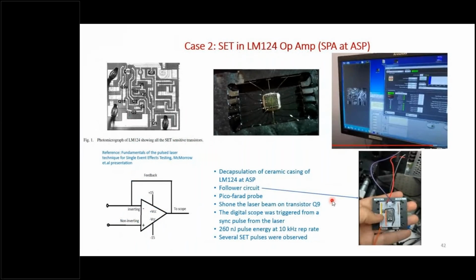The other test study was on LM124. This is an op amp, so we would mount this on a follower circuit. We had a picofarad probe, and this circuit has many transistors, and one of the transistors, Q9, is very sensitive, as was reported in the literature.